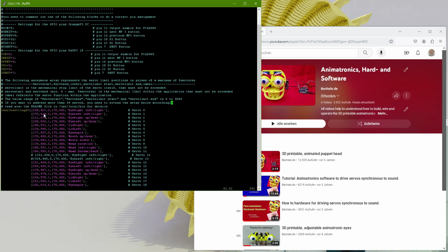These values here are more important because these are the values used when you run the model. A full joystick movement results in a full movement of the limits of your servo, because you have the range of the servo itself. This is normally from 170 to 600. But in the real model, when the mechanics limit the movement of the servo, it might be less.